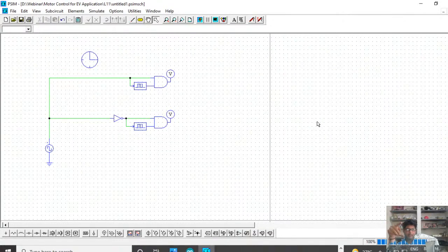We generated the complementary pulses in this way and were successfully able to do it with a small chip. That's why I'm telling you, it is always better to generate the complementary pulse externally using some delay, and using this technique you can use an FPGA, a small FPGA, PL or PLA chip. All these things you can do. There are several techniques to make it practical.